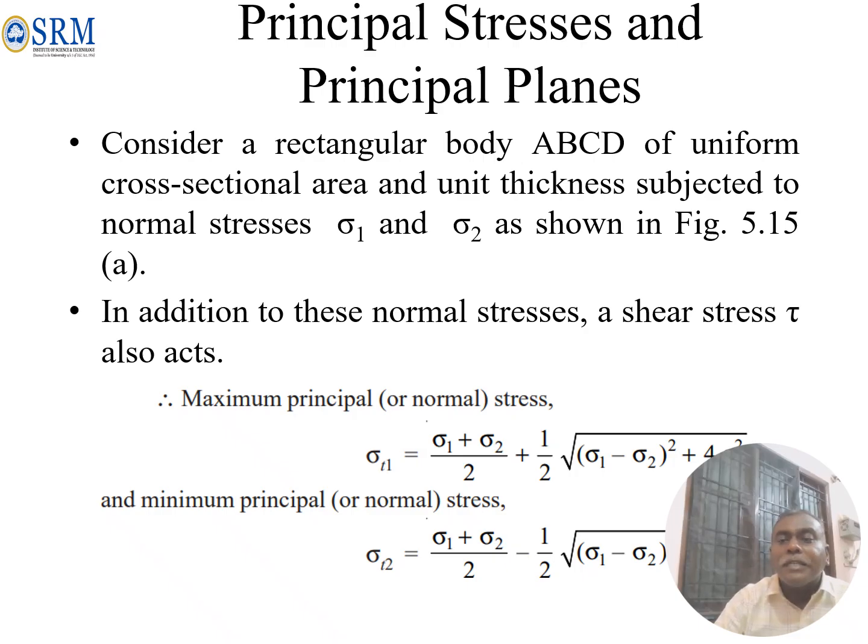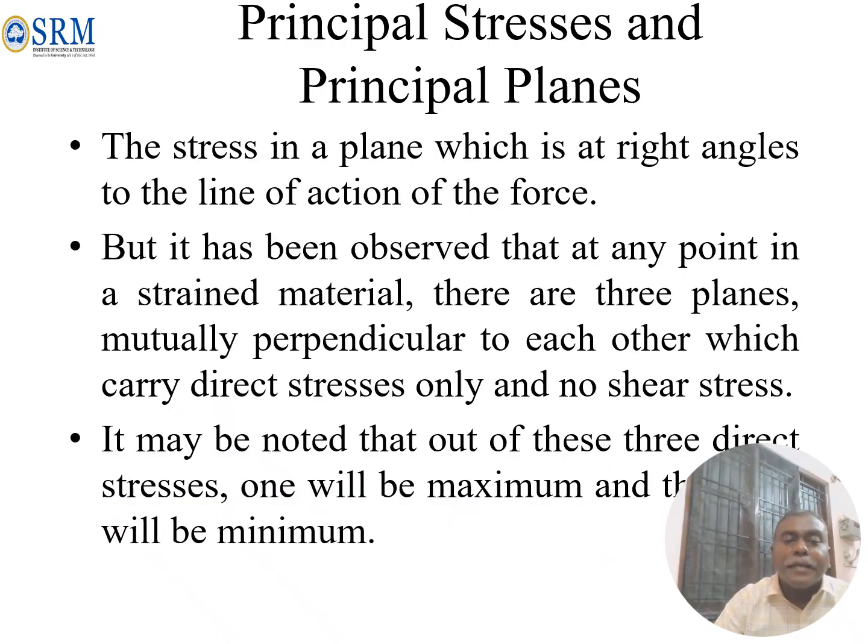See here, the stress is in a plane at right angles to the line of action of force. While solving the problem in principal loading, there are three planes, X, Y, and Z, mutually perpendicular to each other, which carry direct stress only. Direct stress means normal stress. It may be tensile or compressive.